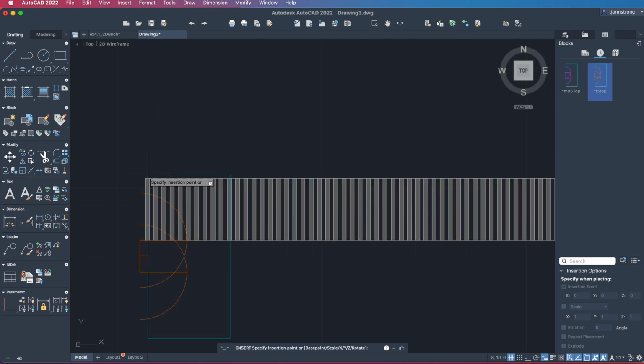That's really important because sometimes people forget that. What it'll do is take the origin, so there'll be a big displacement between the point where you want to insert it and the place where the file is actually hovering in space. So I'm going to come out here to this far point, right there, and click on it. And what I've done is I've inserted my top view of the bench using that block tool.